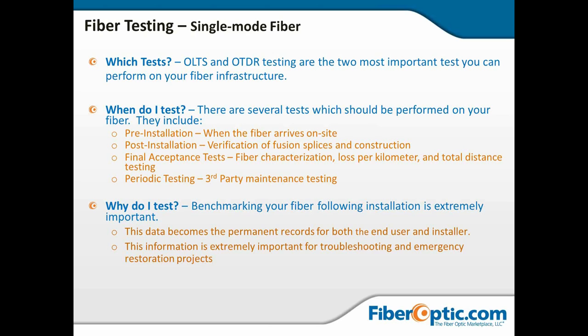So once we get all of that done, then we take our final acceptance tests. This is where we save the traces. We do our loss per kilometer, our total distance testing. Everything is done at this point.